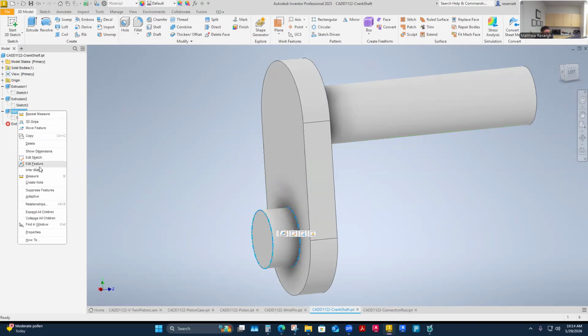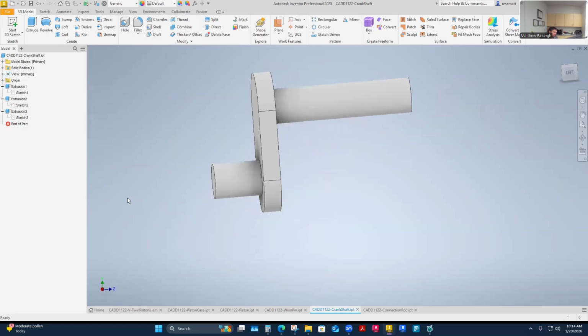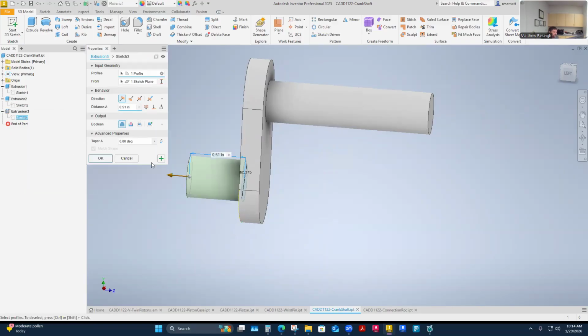So this one here, instead of being the original size times 3/4, I actually need it longer to carry the other one. And it's kind of an odd dimension, but it's 0.51. And we'll see if that's what it ends up being. But 0.51 is kind of the shorter one. That's long enough to hold two connecting rods for sure, and potentially a fastener. So I probably had to adjust that height. Let's see that dimension. 0.51. The extrusion, yep, is 0.51. So I got rid of the original dimension and added that one in.